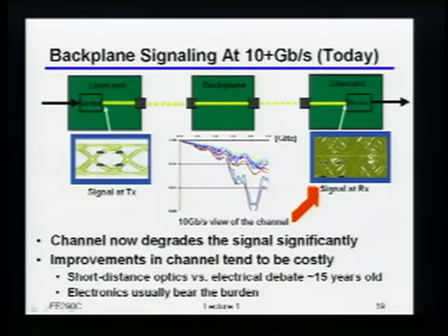Okay? So that's really how the signal would look if you were to go at about maybe 10-ish gigabits per second, maybe even a little bit less than that. Okay? So what that basically means is that we as link designers, as electronics people, have to figure out how in the heck do you decide what the bits actually were, given that I have this huge garbled mess coming into my receiver. Okay?